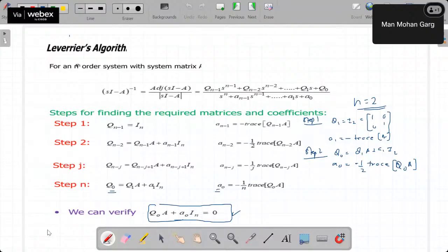Definitely, when we do mathematical modeling even for mechanical systems, we do not take everything into consideration. Still we get good results. If some system has a very fast time constant and some is very slow, what we normally do is neglect the fast one and take care of the slow one, and accordingly design the controller. Though the fast one is there, we neglect it. Why? Because we think that if we design the controller for the slow one, it will take care of this.